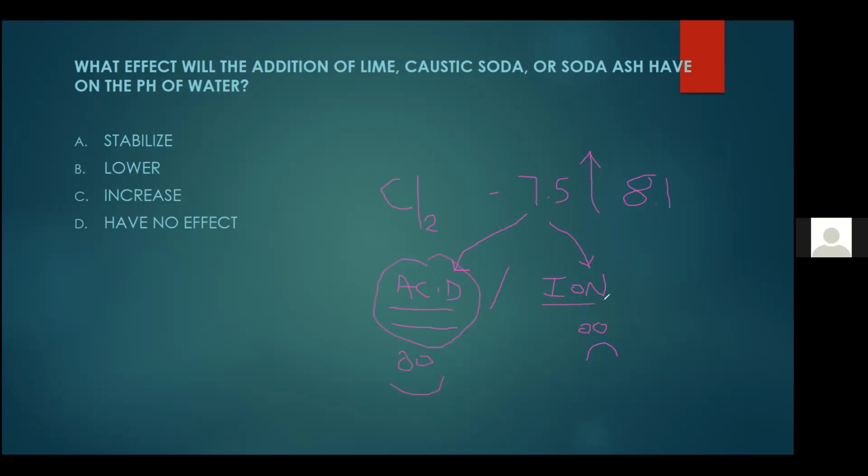As the pH goes up, and as you start getting over 8, more ions, not so good. You might get that as a test question. I see that all the time. The lower the pH, the better that chlorine works. Also, some coagulants work much better at a lower pH. So when you do coagulation, make sure that your coagulant of choice is going to work in the pH that your water is coming in at, or you have to make an adjustment.